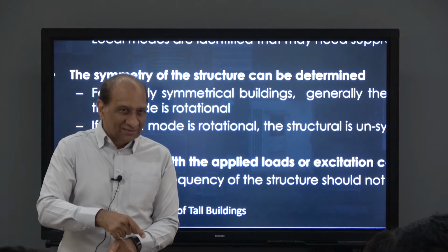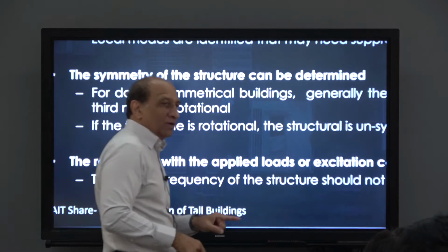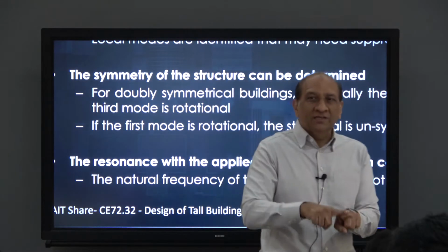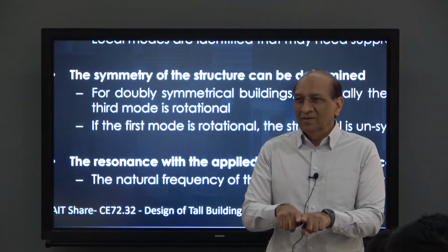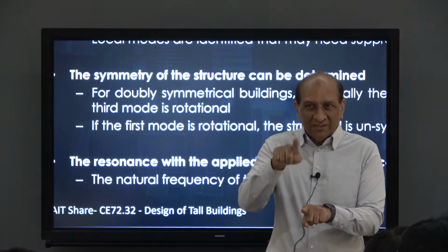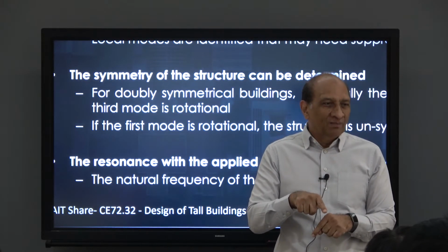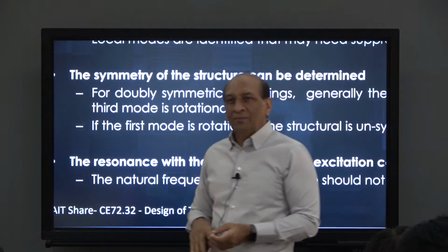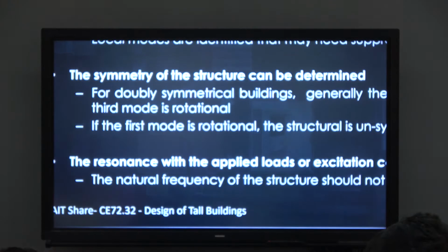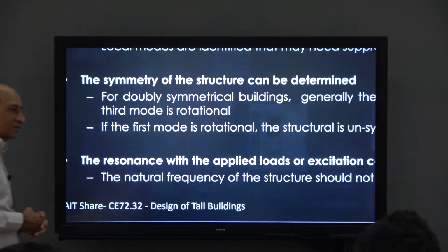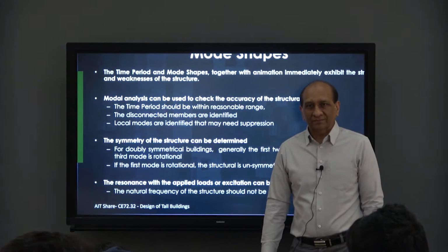Or you can do the other extreme. You can suppress the vibration of a floor by applying a force which is opposite to that and stop the floor from vibrating. Because if the natural frequency is this one, you apply the force exactly but in the opposite direction, and then not let something vibrate. And that is how dampers are designed. That's how so many motion control devices are designed, right? So it is all about dynamic response.